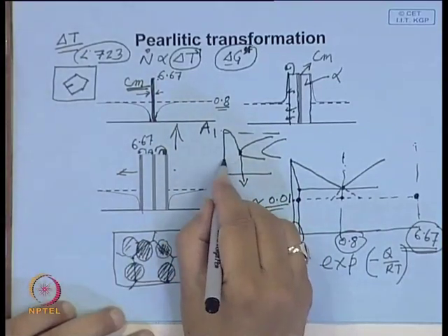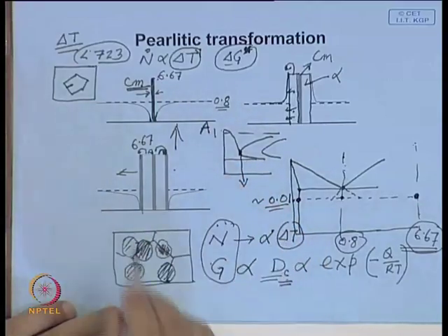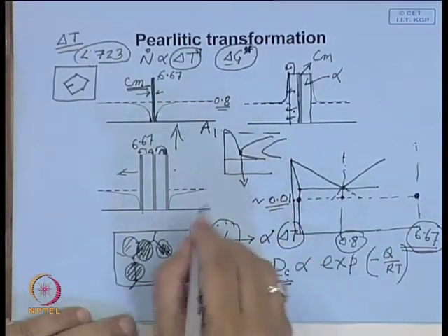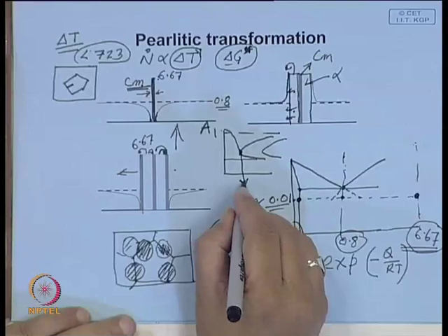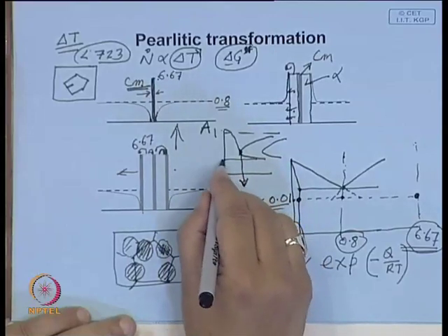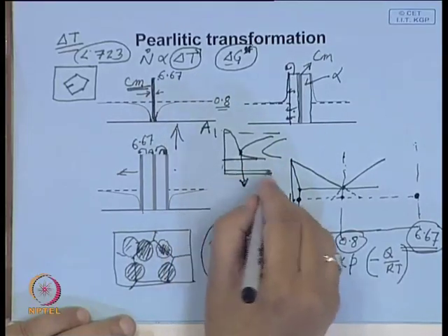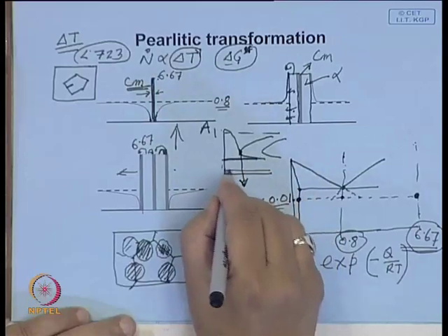austenite into pearlite through a diffusion controlled transformation. But if it exceeds that, martensite is something where we do not allow the diffusion to take place. So that is why it is so fast, there is no C curve, you do not see anything, it is just parallel lines.